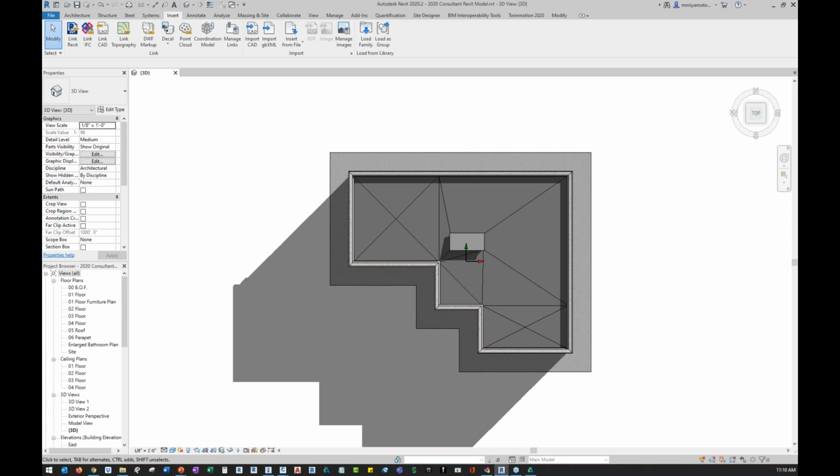It's not instantaneous. That's another thing I should probably mention. When we're working with the cloud, you still have to consider that it is transferring data, and it's using the desktop connector to transfer data for what you're doing in Civil 3D to BIM 360 Docs online. So it's not going to be like, as soon as I click save, boom, it's going to be available for me in BIM 360. You might have to wait a few seconds, a minute or so sometimes, depending on your internet connection and how things are going that day.